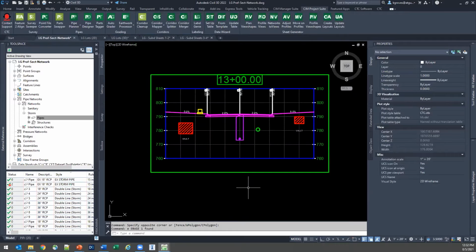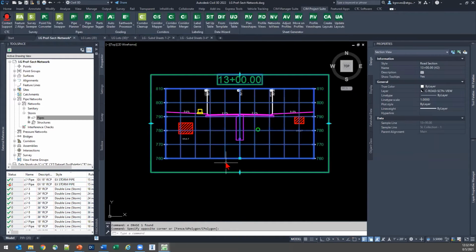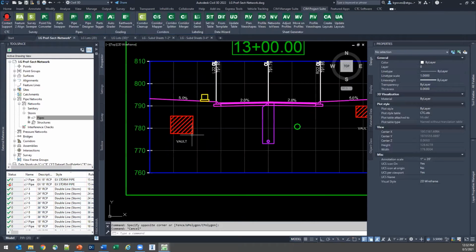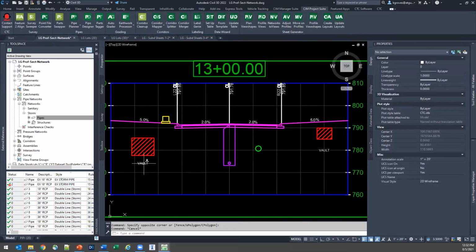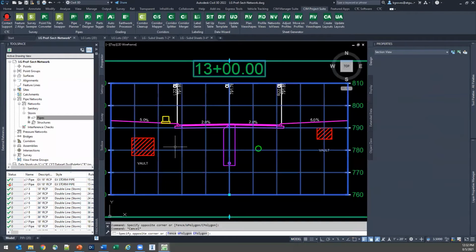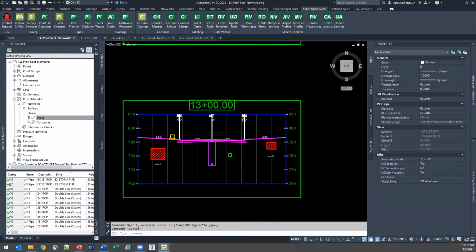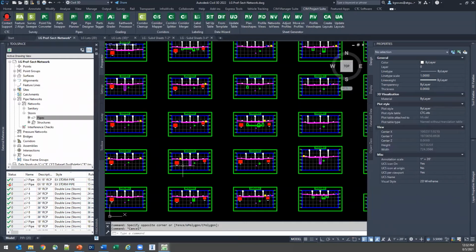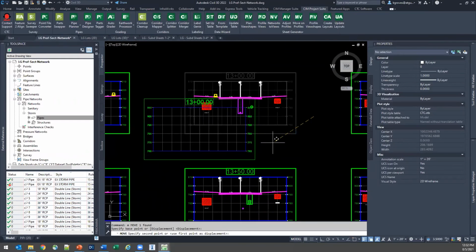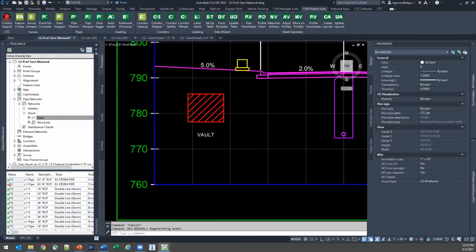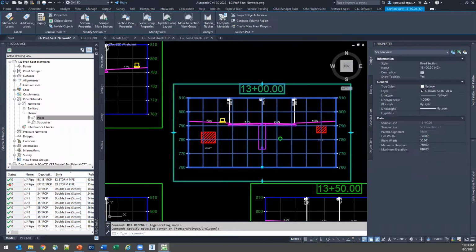Now, one thing that I learned when I was preparing for this webinar, within a version or 3 ago, I don't know exactly when that happened, Autodesk made our section views smarter. So one thing that people complain about if they try to add in mtext or fields or whatever, or multi-leaders, any type of secondary annotation that wasn't managed through your section view labeling or your code set, is that it used to move around if you, for whatever reason, moved your section view. Now, Civil 3D is smart enough that if you move your section view, it's going to keep track of all of the objects within that section view, and it's going to maintain their relative position when that view gets put down in its new place.